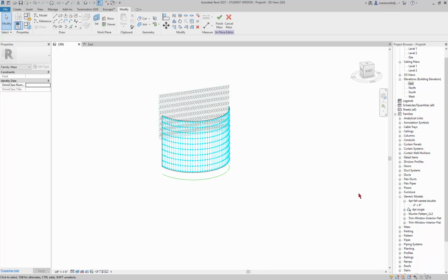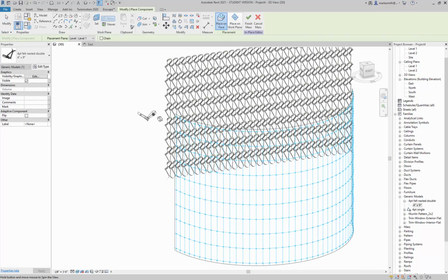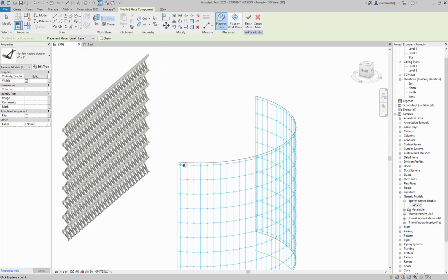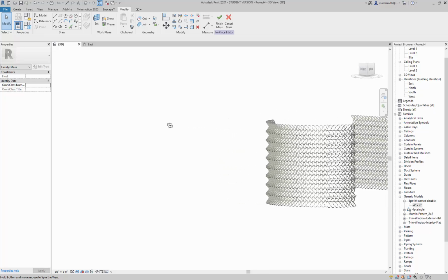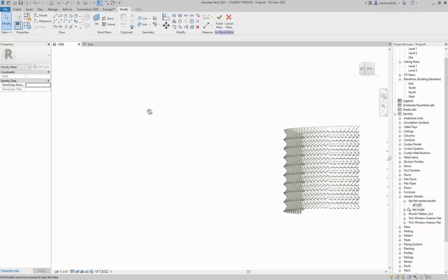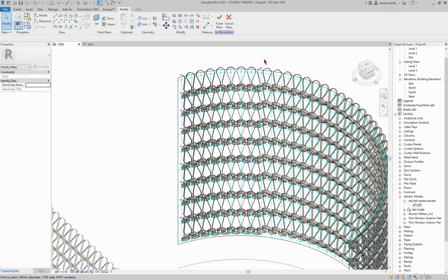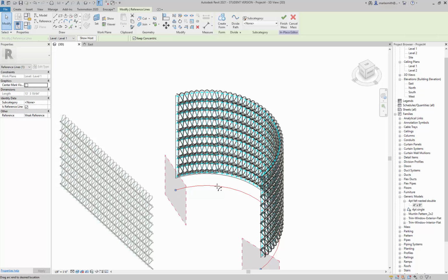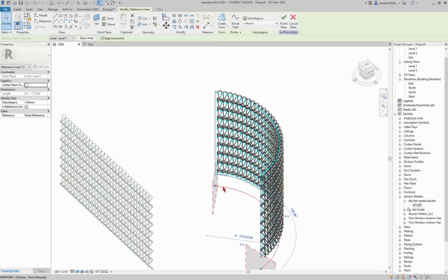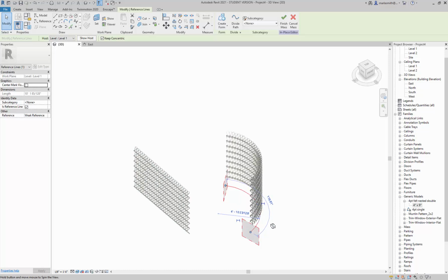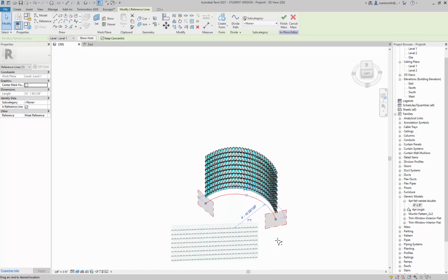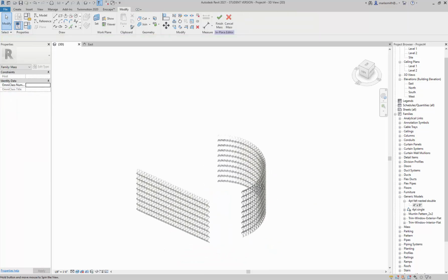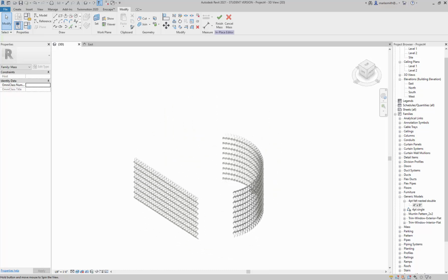So you've got that set up, and then you can come in and drag this guy out and do the exact same thing. You want to be kind of careful. It's really important that you get these guys stuck on the nodes. So just come in, pick that guy, and then you should be able to repeat this around that guy. If it gets a little funky, we can talk about it. Sometimes it tends to flip, and I think there it is. You see how it's flipping right there, like it's breaking and flipping? I'm not sure exactly why it does that. If you pick the little piece and drag it in right past that flip, it'll get rid of it, and then you could come in and drag this the other way. It has to do, I guess, with the way that the curve is working, so you may have to adjust it in order to make it not flip, but we can talk about that later.